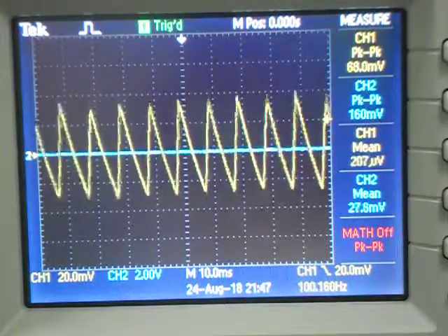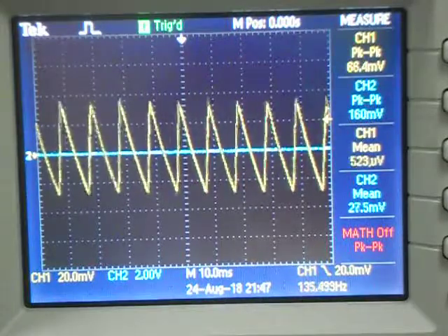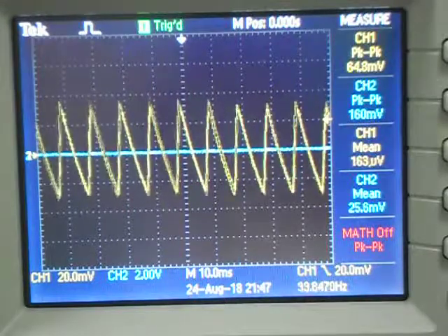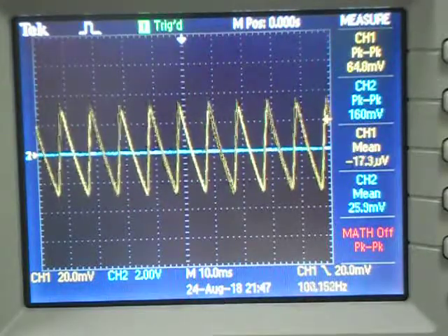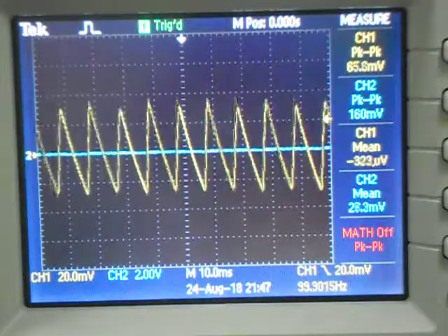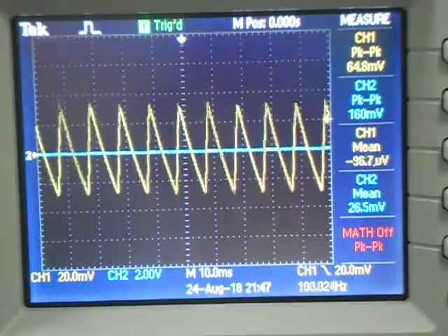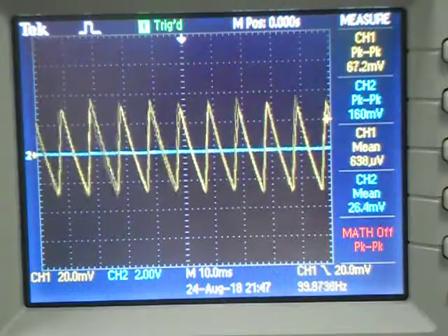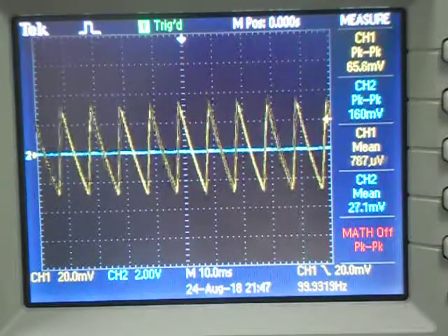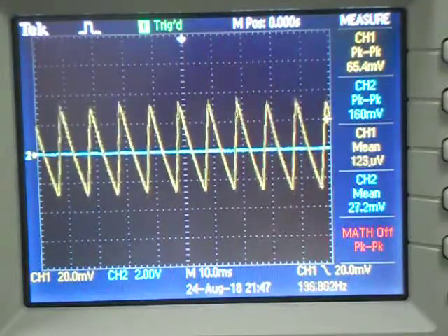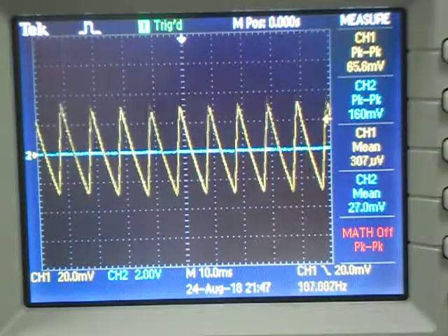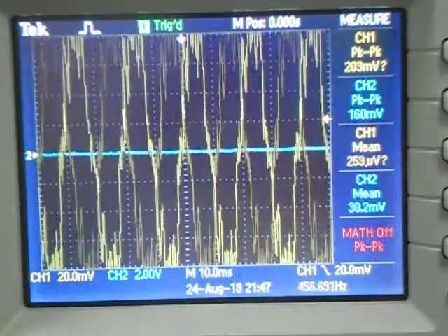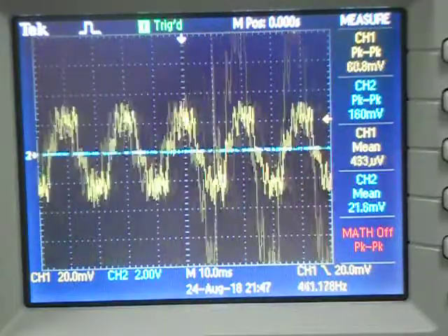Now the important thing to note down is this ripple factor is because I don't have any external load connected to the system. I am seeing the output right across the capacitor, right? So if we start connecting external loads, then we can see its effect on the ripple, right? So for example, first I'll connect a heavy load or high impedance load. So let's take a 1 kilo ohm resistance and connect it across the output, that means parallel to the capacitor.